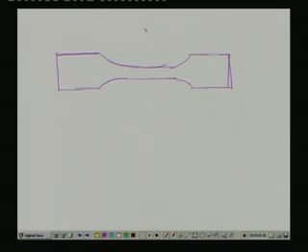Here we can find one section, and let this section be C, and CC and DD are the sections where either of these two could be the points of failure. One here, because the diameter is small and at the same time, due to the larger length, it will be acted upon by a larger bending moment.